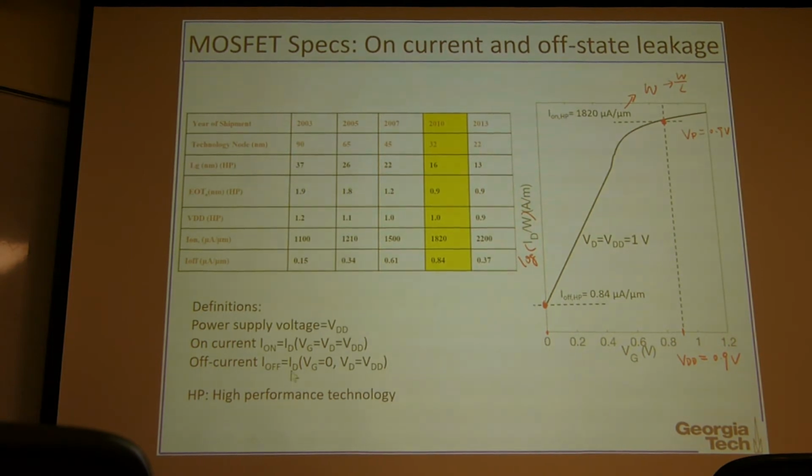But still you have the off current. That off current is coming from your drain, which is the power supply, which means there will be a standby leakage power, which is I-off times VDD. You know, power is current times voltage. So where is this current coming from?